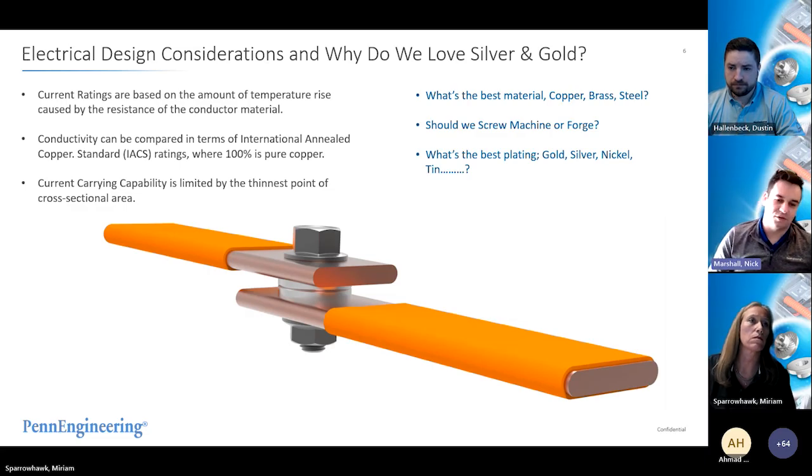So there comes aluminum. Aluminum is not as efficient by volume, but it's much more cost effective and efficient in weight. The difficulty that we have with aluminum, though, is the oxidation layer between bus bars can be much greater and much more of a challenge. So we really worked to figure out what's the best combination that we can give to customers when we're talking about solutions for these terminals.